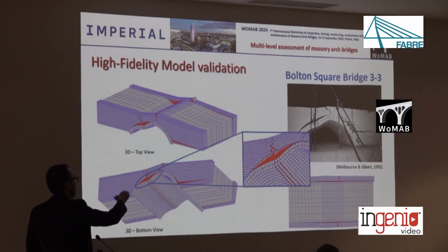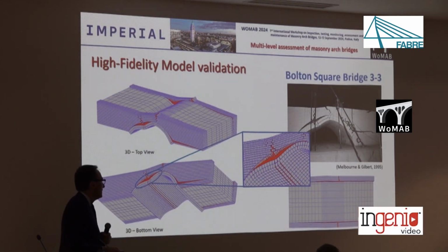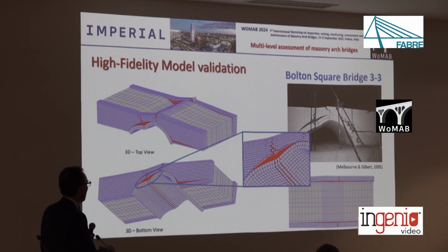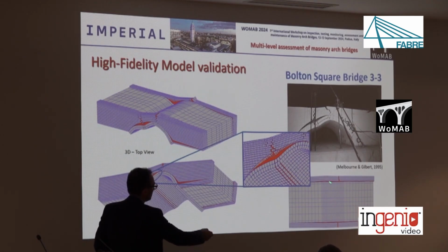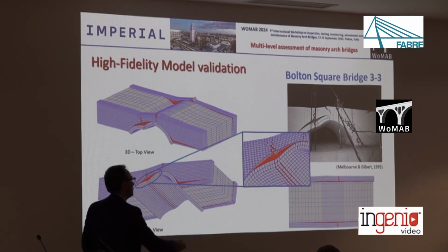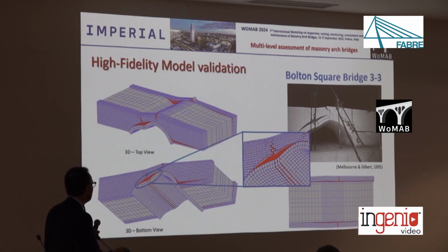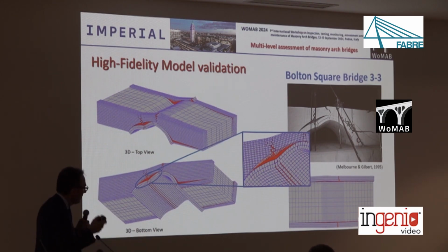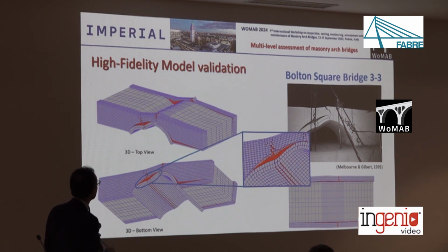and complex cracking in the arch, a combination of radial cracking and ring sliding. And of course, damage in the spandrel wall. In this case, you see the out of plane deformation of the spandrel wall is limited, which indicates a reduced 3D behavior because the structure was loaded by a knife edge load applied throughout the whole width of the bridge. So we validated the model. This is just an example, but we performed several other validation examples. So we confirmed the accuracy of the predictions.